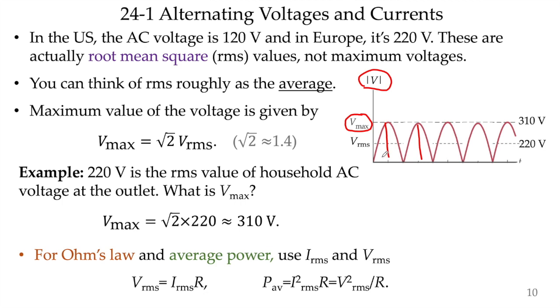So on average, the voltage is not 0. The voltage is not maximum, but on average, it's going to be somewhere in between, not exactly the middle point. You have to use some integral and averaging to calculate it, time averaging. This is time. You can take the integral of these curves. It's basically sine squared, and take the time average. So basically divide by the period of time.